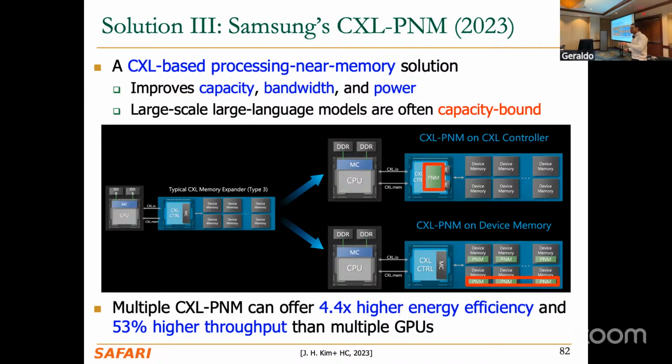In the end, the computation they are offloading is the same, but for different scales of models. The CXL one you use for larger models, the LPDDR one for smaller models on the edge, and the regular HBM one for medium scale models, but in the end, it's just transformers.